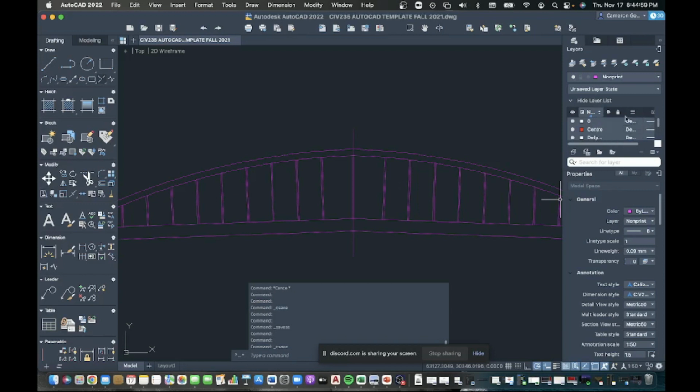So what I'm going to do here is, you can see this layer panel here, and there's a spot here. It's going to look like three stacked rectangles with a little pop-up. It's just these three stacked rectangles. I'm going to click on that, and that creates a new layer. So you can see it's asking me to make a name for it. Default is Layer 1, but I'm going to call that Center.